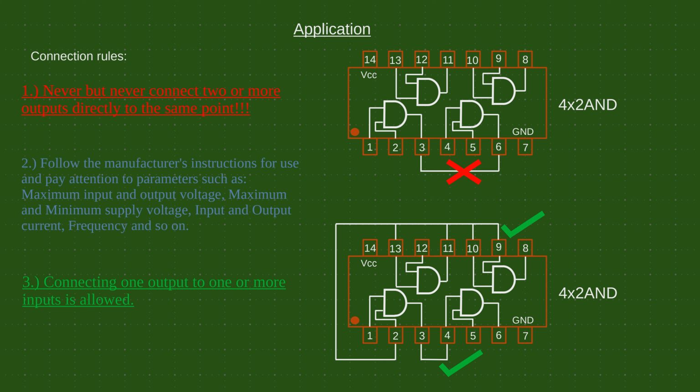It should be noted that there are different versions of these logic gates, and it is up to you to choose the type that will give you the best performance with a good price-quality ratio. The most common are diode logic, diode transistor logic or DTL, direct coupled transistor logic or DCTL, transistor-transistor logic or TTL, NMOS logic, complementary MOS or CMOS, and so on.